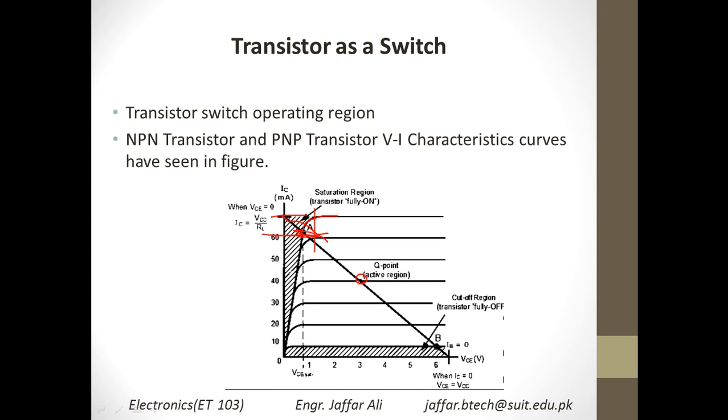After you have received 90% of the final value, the switch is termed as generally on. This is by convention: let's say your final value was 100, and if you have reached the value of 90, then after 90, this will be termed as on. So from this point, or from this time actually, let's say this was 1 and this point was 2. After you have received this point 1 and you know that this is approximately 90% of the final value, you can term this as turn on switch.